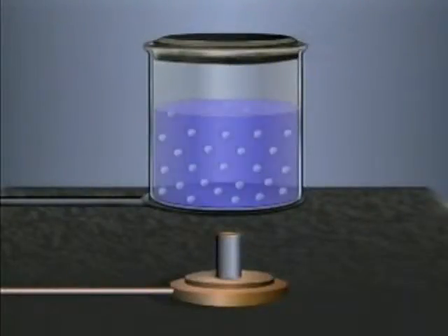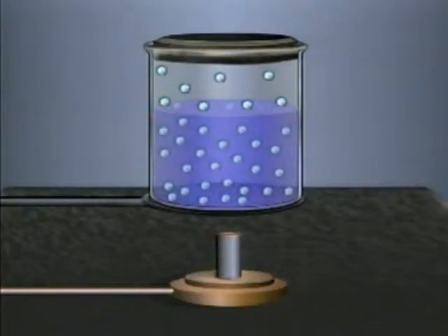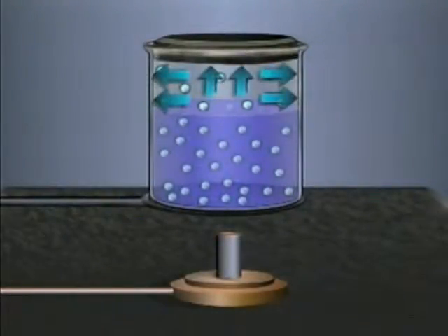One of the factors that affects the distillation process is pressure. One type of pressure is vapor pressure. Vapor pressure is the pressure exerted by vapor molecules that escape from the surface of a liquid. To get a better understanding of vapor pressure, let's look at an illustration of a closed container of liquid. In any liquid, some molecules escape the surface of the liquid as vapor, and some of the escaping vapor molecules return to the liquid. The escaping molecules create pressure by colliding with the container's walls.